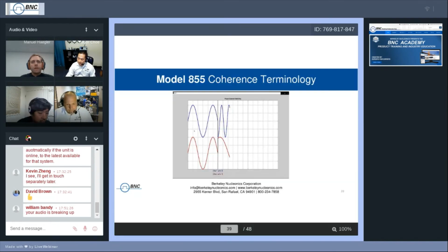All right. So now, for what kind of application can phase coherent switching be used? In phased arrays, for example, it's possible to change the direction of the waves by setting a phase shift between different antennas. Having outputs that are phase coherently switched can greatly simplify the work, since the phase relation between two signals is known when switching them to a certain frequency.